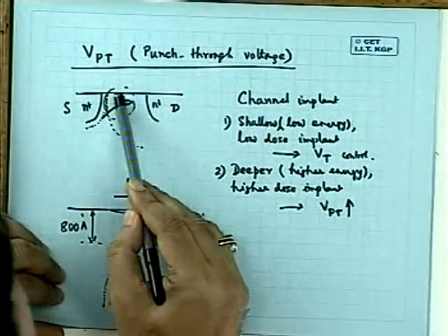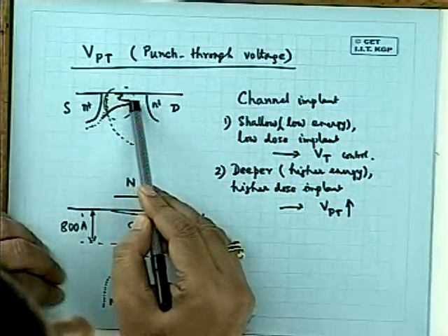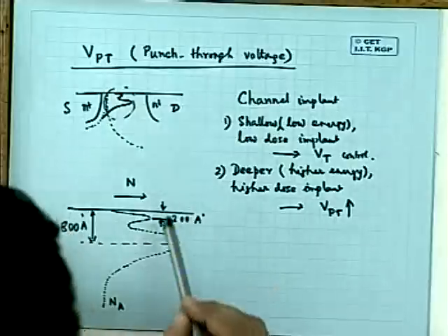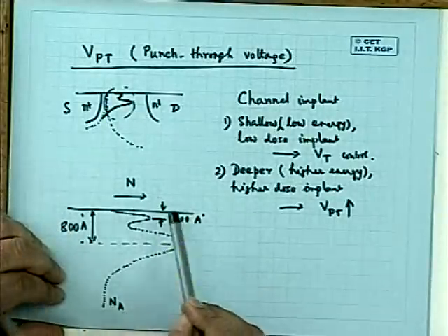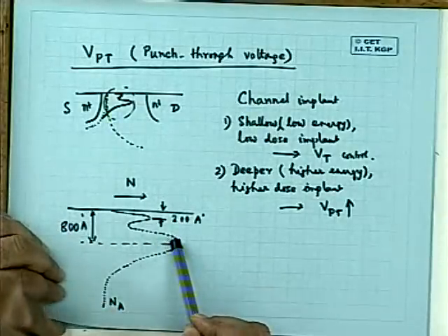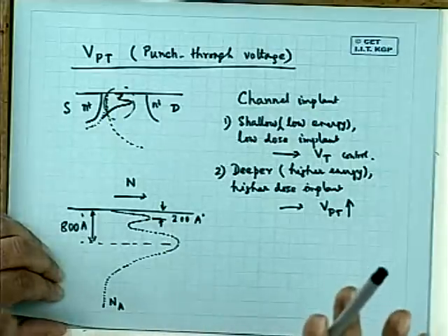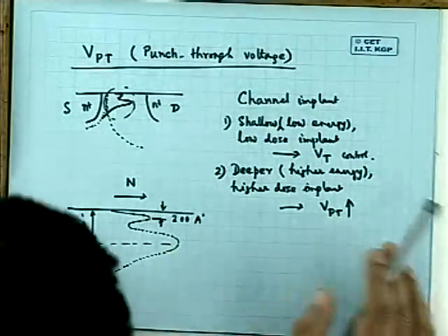If it is uniformly highly doped, the breakdown voltage will be reduced. But if it is not uniformly highly doped but localized highly doped, the breakdown voltage will be reduced definitely, but not that much. You have to make a compromise, and that calculation is not a simple task. The calculation of breakdown voltage with a non-uniform channel is quite a difficult task.